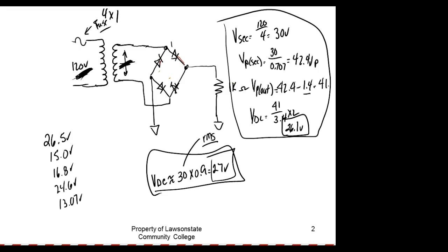We use what we call second approximation anyway, because the diode drop varies a little bit between when it turns on and when it actually conducts, and it varies the more current you put through it. I think the 914, when you run 1 amp through it, could actually drop up to 1.1 volt. But still 7/10 is okay, right? Because what's the difference between 1.1 and 7/10 of a volt? 400 millivolts is not that much. So instead of trying to figure out the exact drop across a diode, we use 7/10 for silicon, and we call that the second approximation.